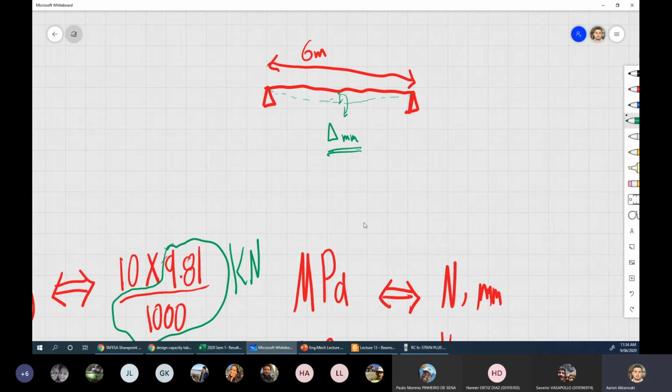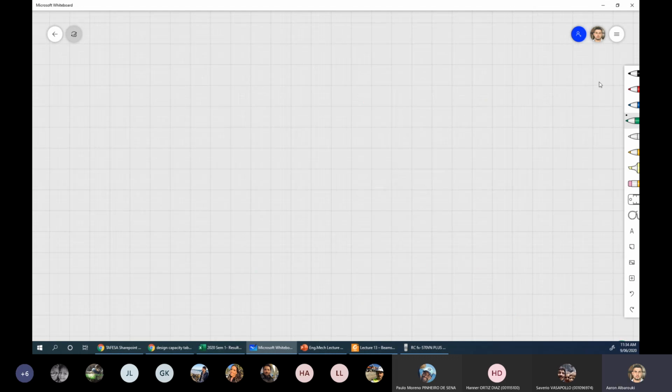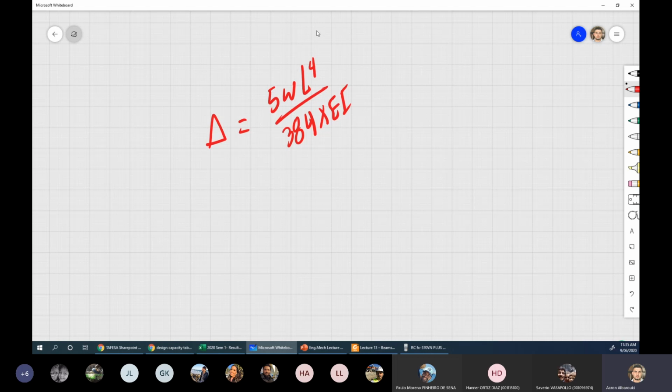Other than that, I gave you an example before, didn't I? Just to remind you, for calculating deflection, which we looked at briefly, for a simply supported beam: 5WL to the power of 4 divided by 384 times E times I. W could be in kilonewton per meter, kilonewton per millimeter, or newton per millimeter. L could be in meters or millimeters. E could be GPa, kPa, MPa. I is millimeter to the power of 4. If you try to think through it too much and make your units cancel each other, that will take a very long time. Any of these formulas will work 100% correctly if your units are uniform.